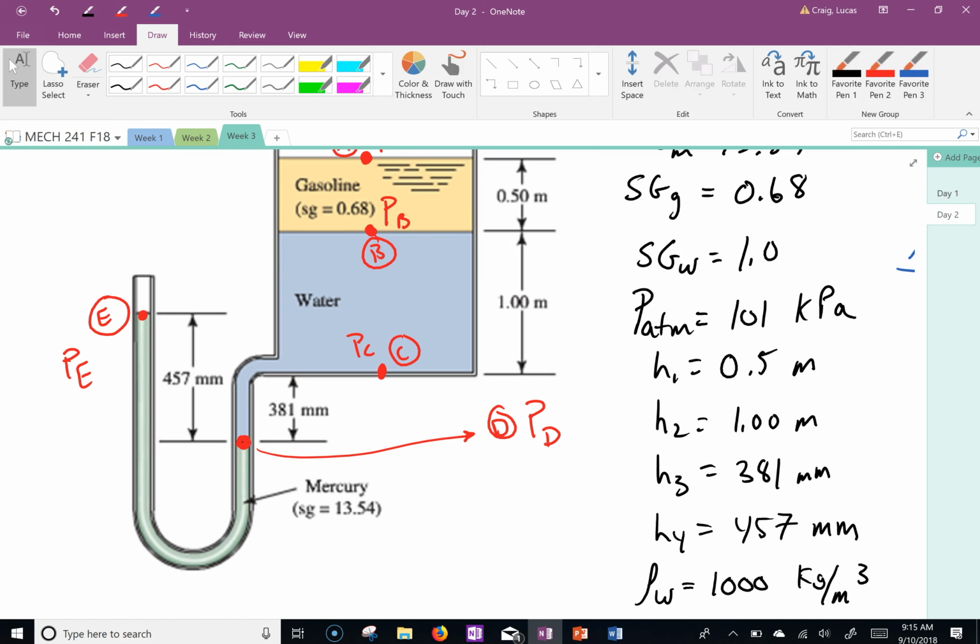That's the top pressure. What's below that? PC, or you could do PD, right? Because it's the same fluid, because it's all water here to here. So technically, you could just add that and that depth. Okay, because if you looked at the equation, it's the top pressure plus rho GH. Only affects height. So for as long as you have the same fluid, you can just add those two heights together. Okay?